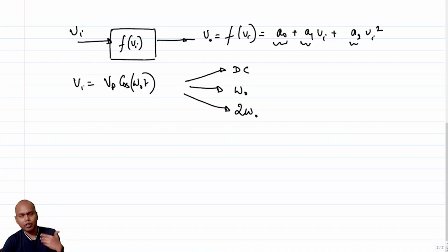In fact, you might not even be sending tones, you will probably be sending aperiodic signals or some signal which has some random information, right? So a more accurate way of representing distortion in an RF system is to model a system in which multiple tones are being sent simultaneously. A simpler version of it for analysis purposes is to send two tones which are close to each other. That is a more realistic